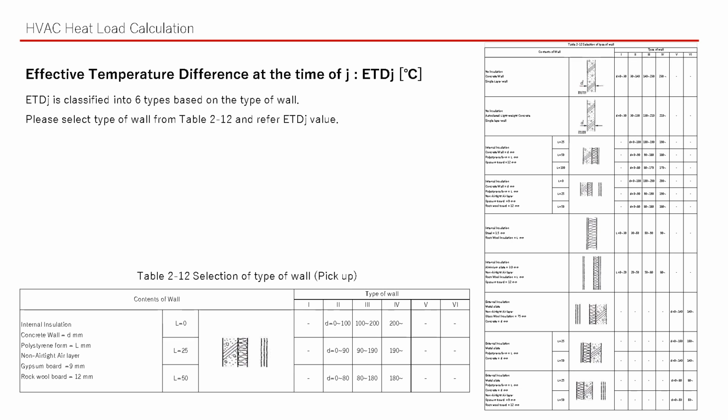Next, the effective temperature difference, ETD. The reason we do not simply use the external and internal temperatures is to make the calculation more accurate by considering the heat storage characteristics of the walls and roofs.